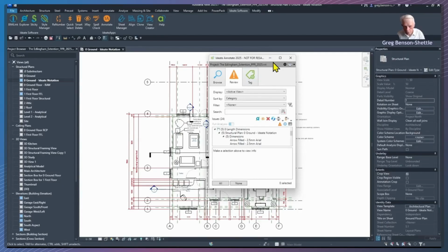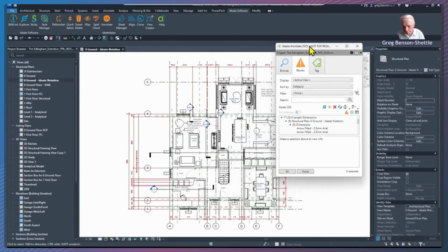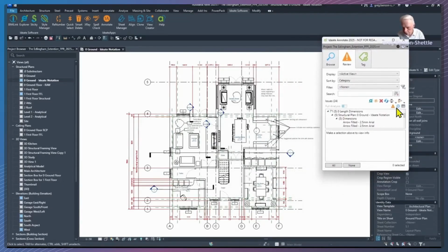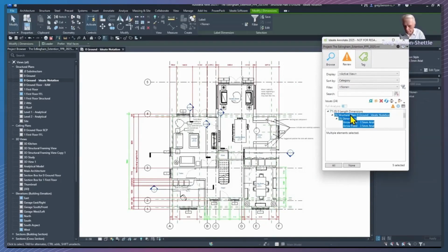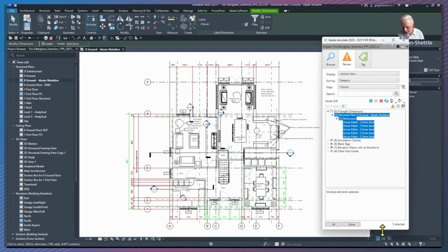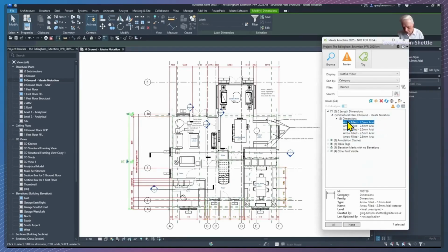So I'm going to move this over to one side. Like so. Now then, watch. I click on this set and look, it's highlighted in green because that's my selection color. It's highlighted in green, all these elements. Now I'm going to make this a bit bigger so we can see all the different bits. And you can even go down and look at individual elements where it's picking up these different faults. Okay, so you can therefore zoom in and we could go in and correct these.